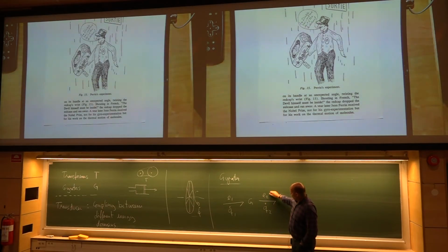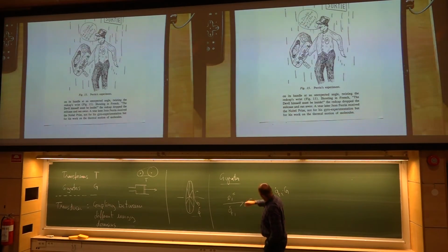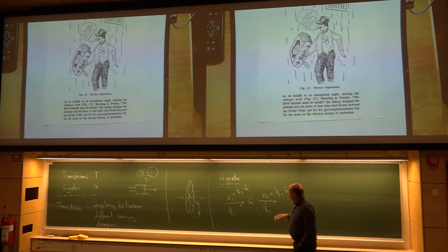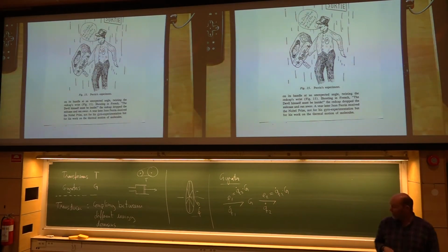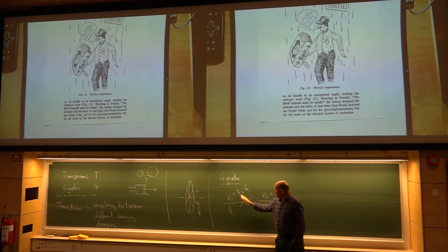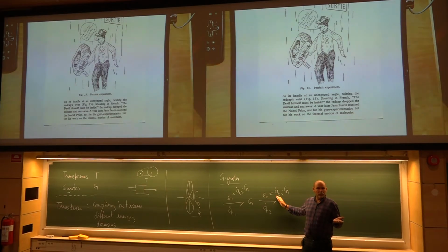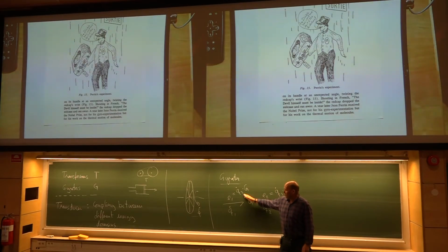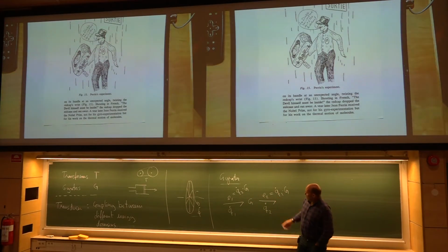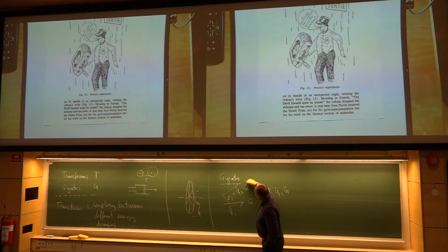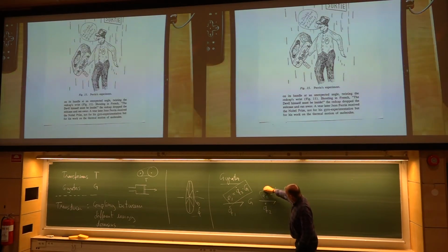So the F at number 2 equals the flow number 1 multiplied with a G. F at number 1 will be flow number 2 multiplied with G. So there you have the two equations. And you could use, say, the first one as a definition of a gyrator, then the other one will immediately pop up due to the fact that we should have no loss of power. So if one is given, then you have the other one there. But these two equations will now be the definition of a gyrator.